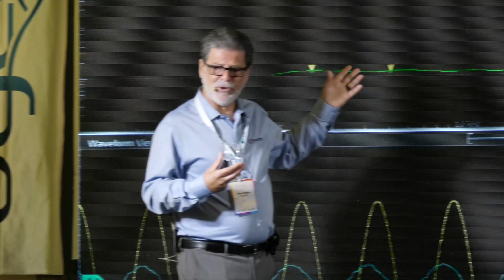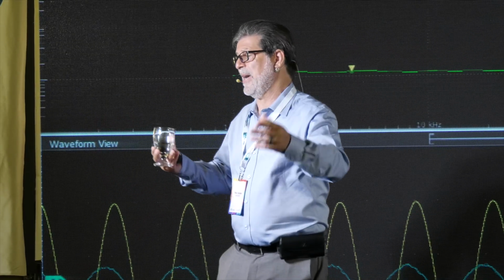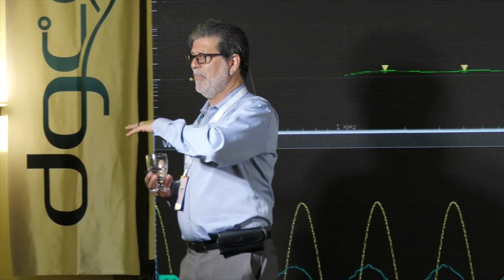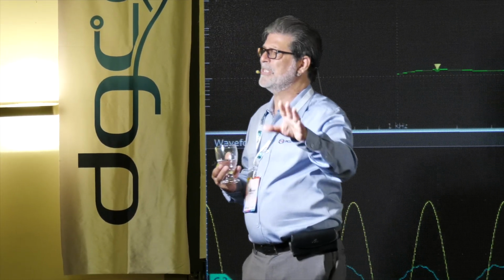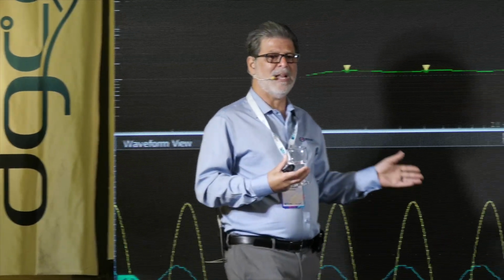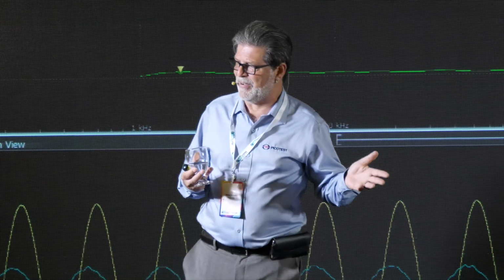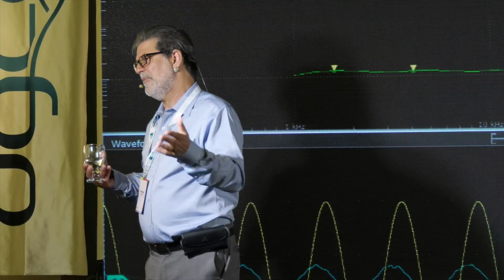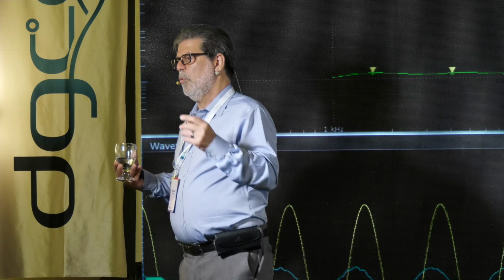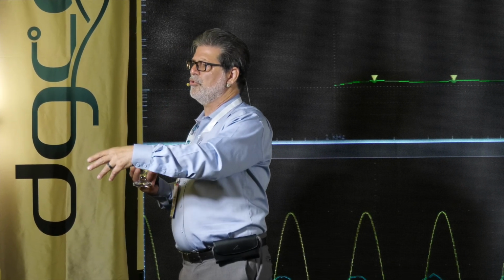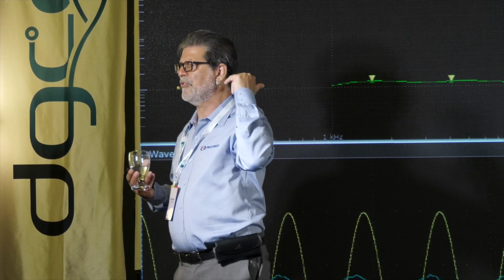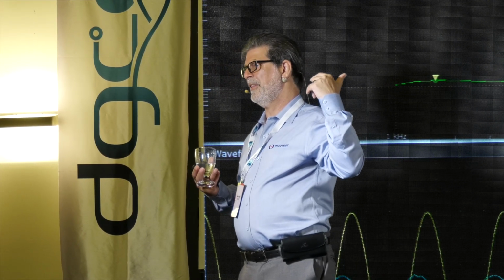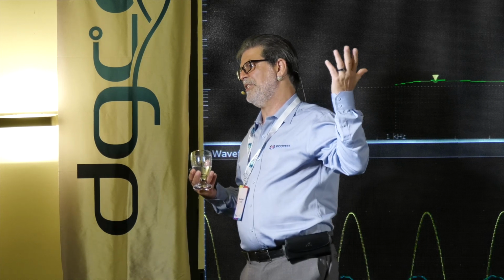If you go back to that first slide I showed, and you guys do have access to the slides, I showed our fixed version, which is flat, and I showed the TI version, which was not flat. The TI version has a peak impedance of about 125 milliohms. The flat version is 10 milliohms, 12 and a half times better. What TI is doing with these nonlinear controls and digital controls is to make up for the stupidity of that huge peak that they put in their impedance curve that they should have just designed out in the first place. It was easy to do.